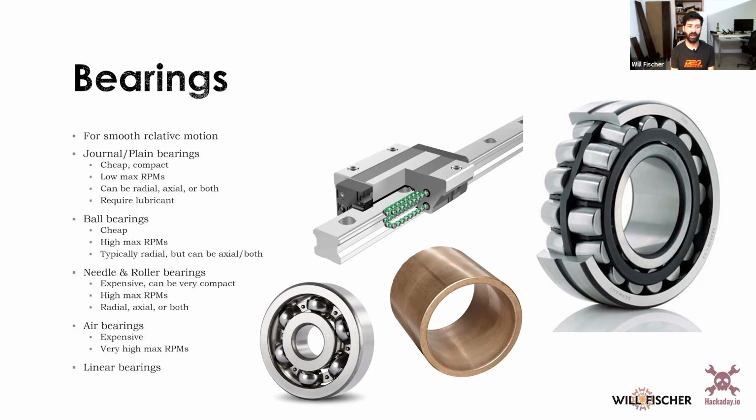They're cheap and compact. They can't get to super high RPMs, and they do require lubricant. You can get what's called self-lubricating bearings, where they put lubricant into the bearing already and it's slightly porous and seeps back out. It's super useful. You can use them to hold a radial load, meaning I've got my shaft and my load going on the radius to that shaft. Or an axial load, which means a load pushing along the axis of my shaft, and you can get both depending on the shape of the bearing.